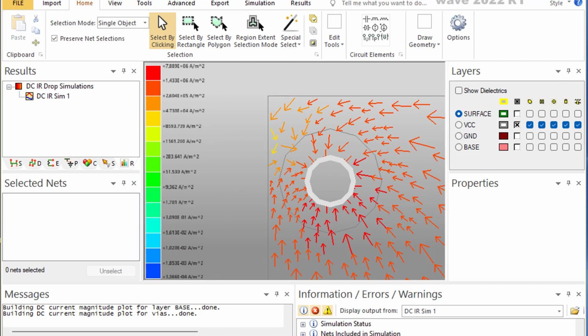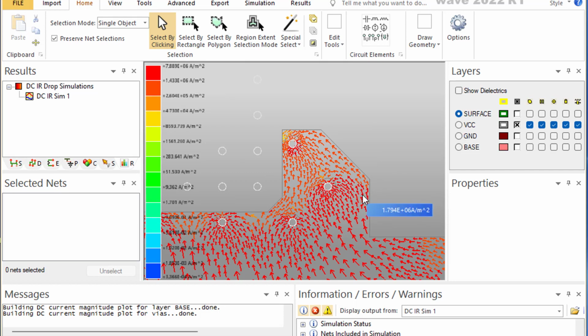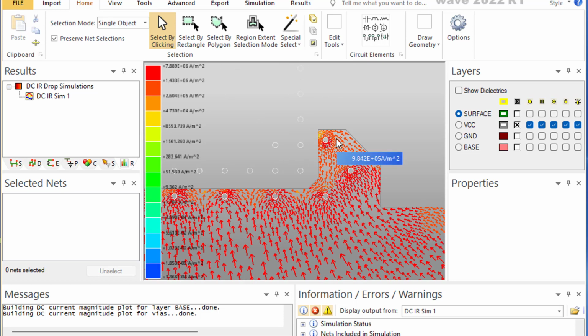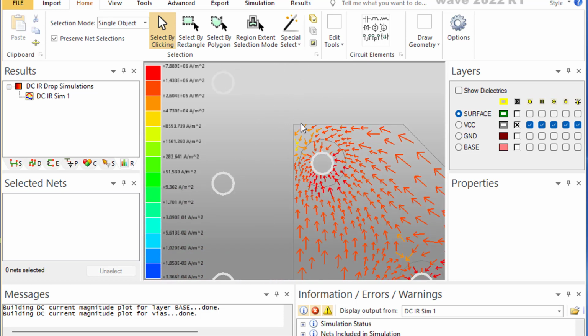Always, even with DC applications, avoid having sharp corners. Always make them round corners. It doesn't cost anything to make them round. But keeping them sharp will have a potential for creating ESD issues in the long term, and you don't want to do that.